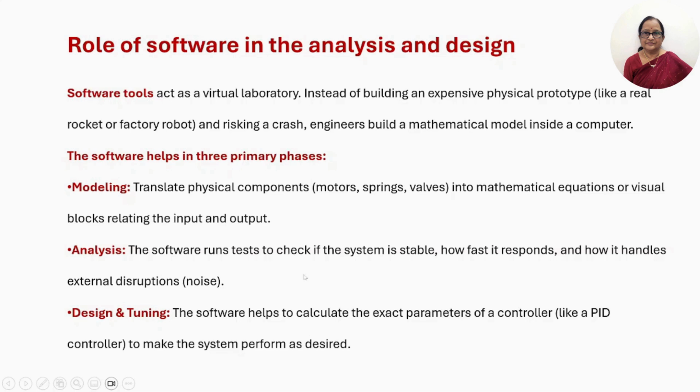The software runs tests to check if the system is stable, how it is responding, whether it is fast or slow, whether overshoots or oscillations are there, and how it is handling external disruptions. All this comes under analysis. And the third phase is design and tuning. The software helps to calculate the exact parameters of a controller like a PID controller to make the system perform as desired.